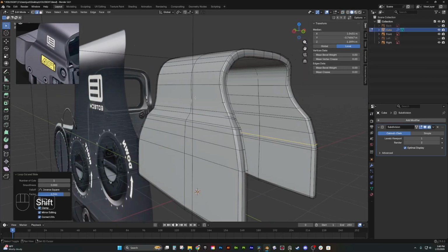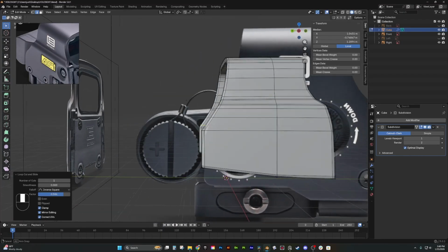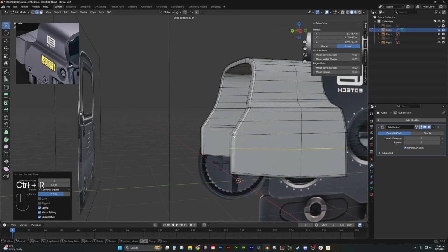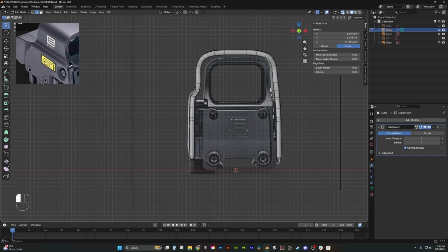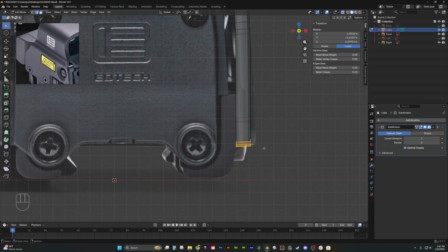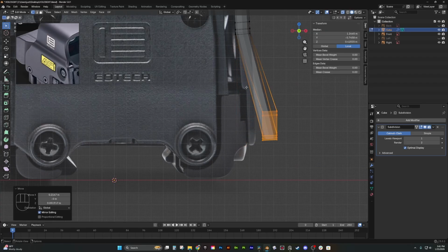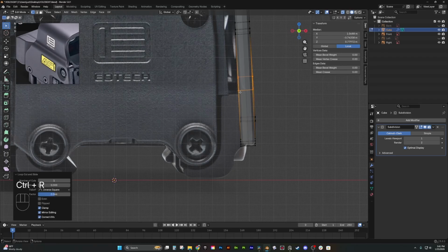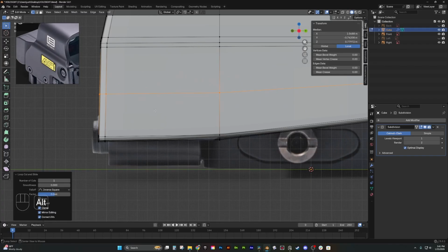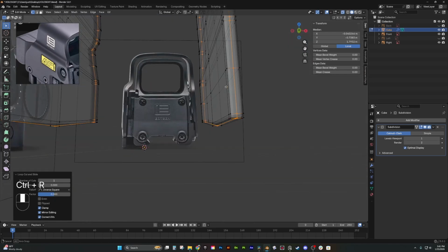Now I'm just giving it a good old-fashioned ocular pat down, seeing if this respects the shapes that were originally in the reference, and they pretty much do, except we have to tighten this corner as well with some control loops. And we might up the difficulty just a little bit here, and we'll notice that if I drag all these edge loops out, make sure we get them all, we'll notice it kind of dips inwards before it stops. So I think we can handle that with an edge loop at the right location. It seems like it'll do the right job for us, and I'm pretty sure that'll go on throughout the whole thing. And we can add a control loop right here.